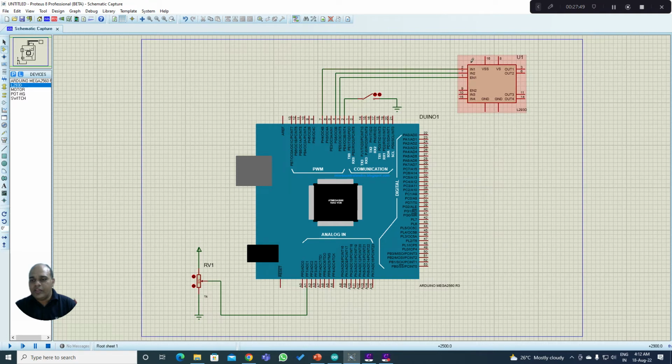So here I have connected in1, in2 and the enable line. We need to give the supply voltage for your IC to work on. So for that, I am going to go to terminals mode again, select the power, and connect it to your supply voltage pin.